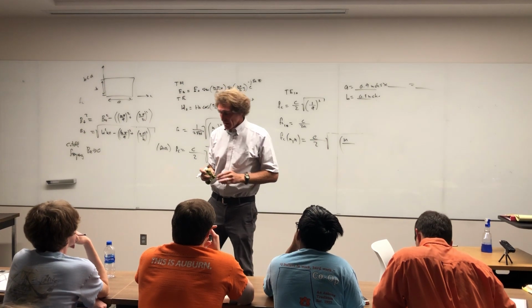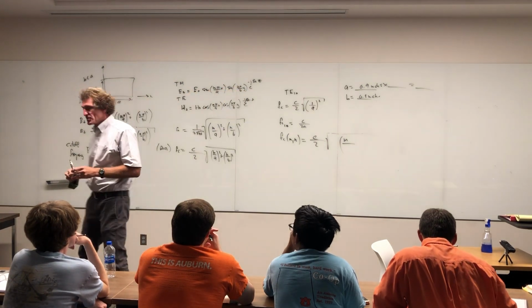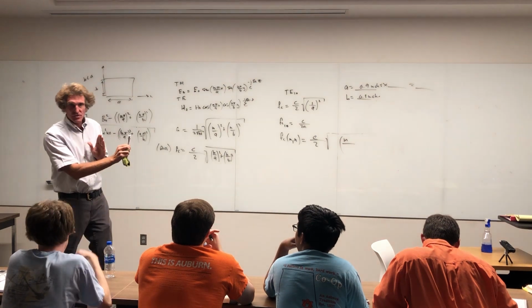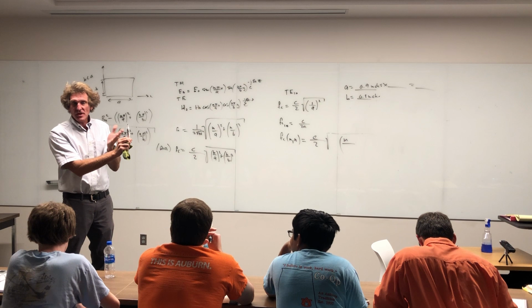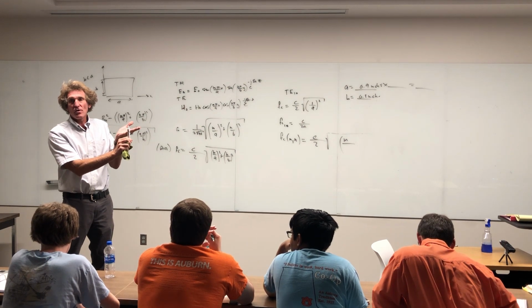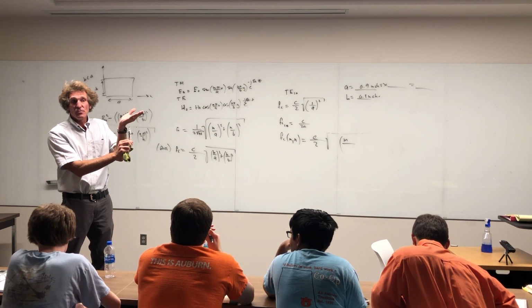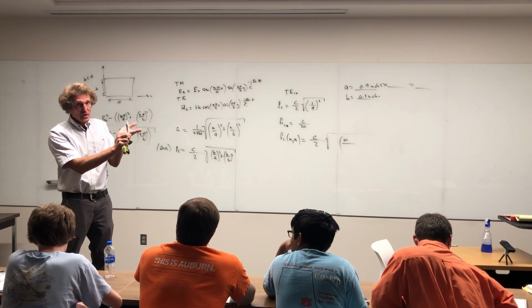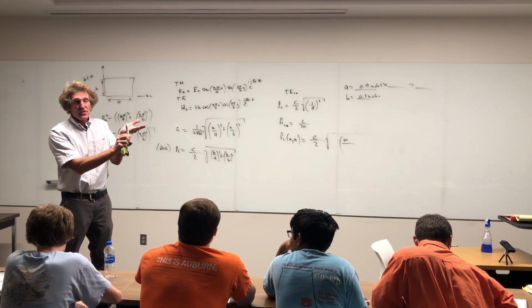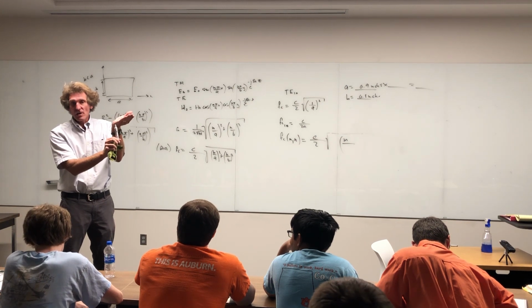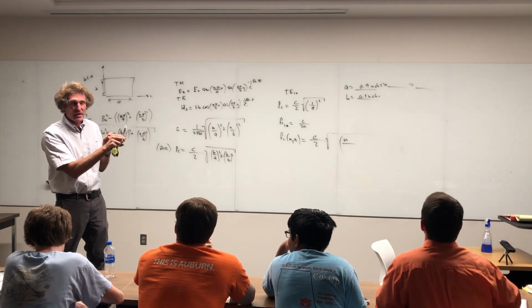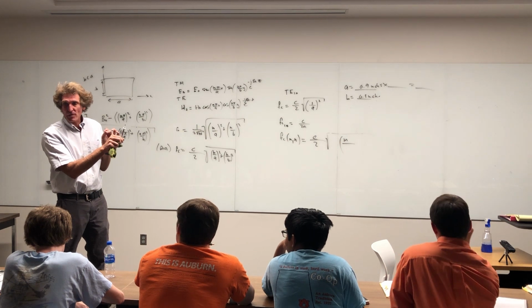We didn't get there yet, but the velocity that energy propagates down there has to do with the mode it's in. What you normally do is drive a waveguide just at a frequency beyond the 1-0 cutoff frequency, but not to the 2-0, all right? So between 1-0 and 2-0, you drive in there. If you drive above 2-0, then there are 2 possible modes. There are 2 possible velocities for energy or power propagation. And what that does is garble everything.